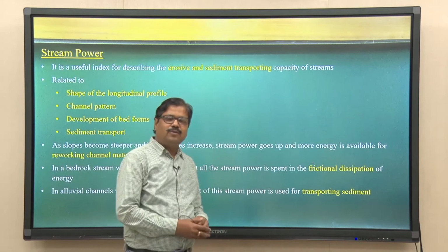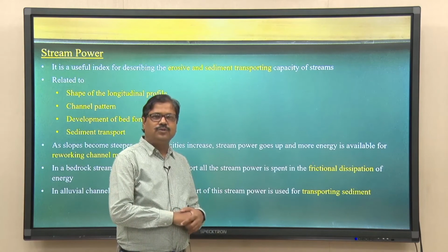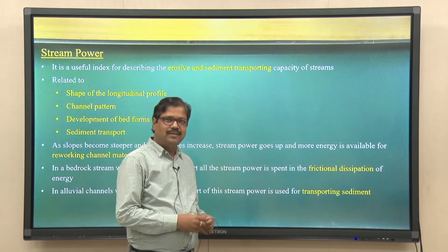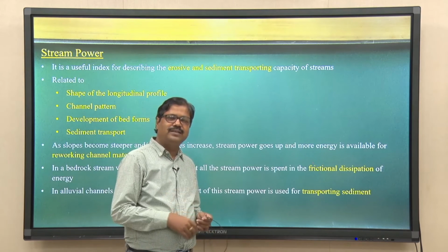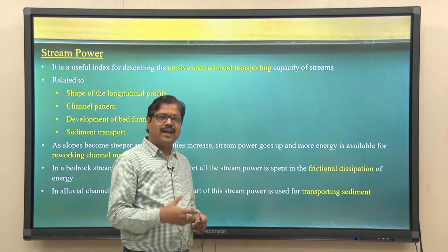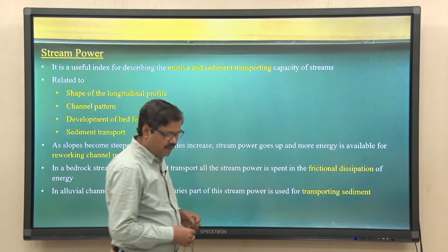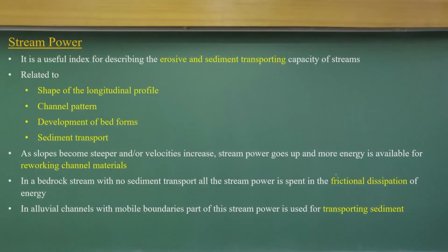Another point I want to introduce is stream power. Stream power is nothing but the potential energy loss in a stream of length L. That clearly indicates that, based on stream power, we can know how much sediment transport capacity or erosive power the stream has.